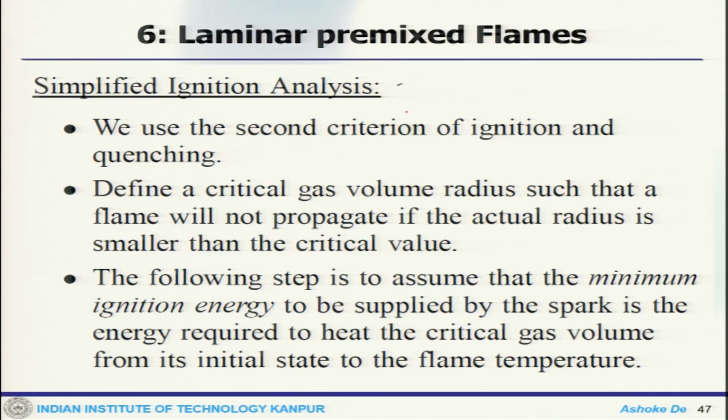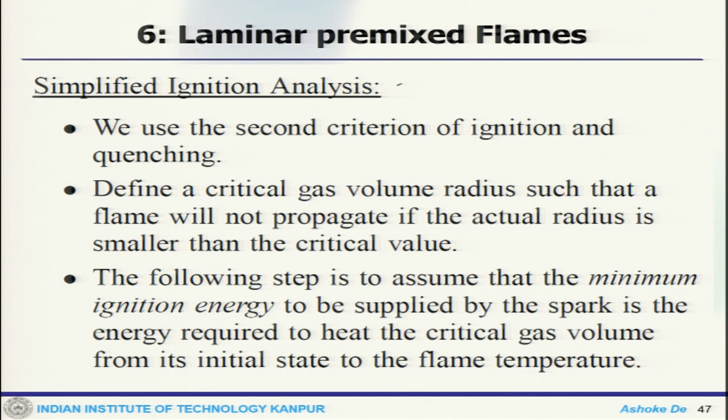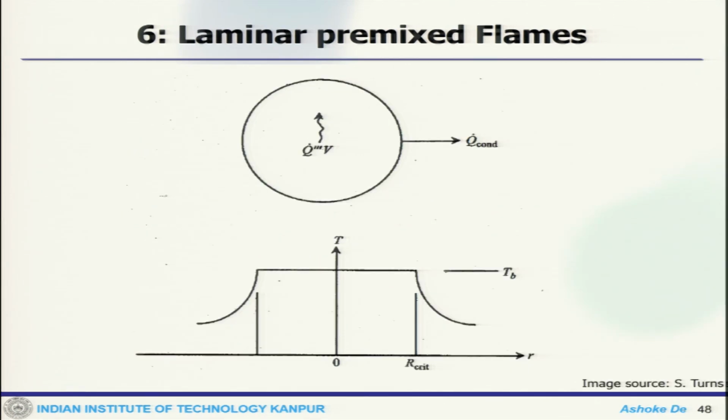Welcome back, and let us continue the discussion of the ignition analysis of premixed flame. So, we are doing some simplified ignition analysis, and this we already discussed. What we want to look at is the minimum ignition energy, these are the application areas, and this is the analysis of how we are going to do it, because basically we will define a gas radius and then use the spark to find that out. So, this is the gas volume radius,